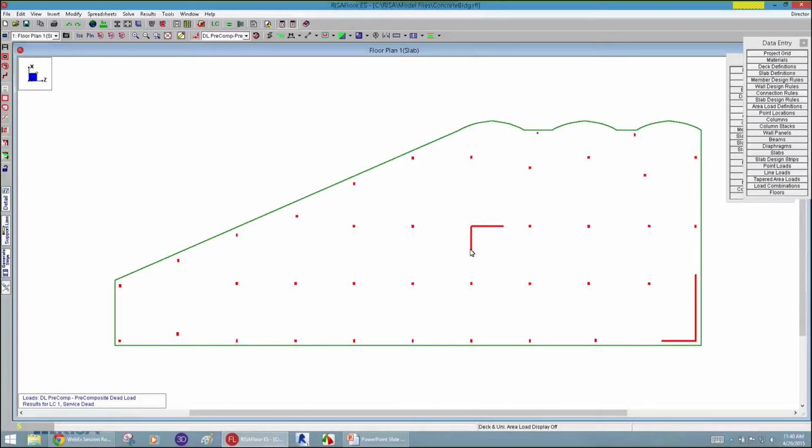We've got some shear walls, and as I mentioned, you're going to make sure that you place all of your columns as lateral columns. That just means that they're going to go over to Risa 3D and help support that semi-rigid diaphragm when we get there. So we've got some lateral elements in this model. This is just 2 stories, and Risa Floor carried all the gravity loads down the structure. It went and designed all those gravity loads.